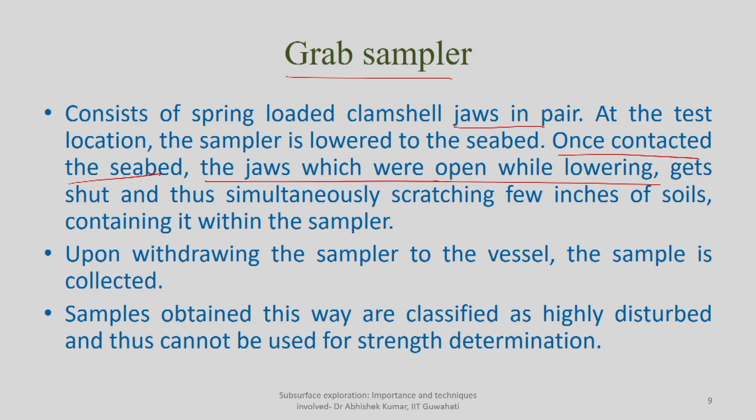That is how it is also containing the sample into it. So this is called a grab sampler. Just like anything you are grabbing, this sampler goes to the seabed, grabs the material, and brings it onto the surface. That is why it is called a grab sampler. Upon withdrawing the sampler to the vessel, the sample is collected. That is how you can collect the sample from the seabed material.